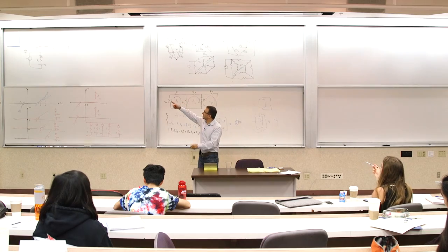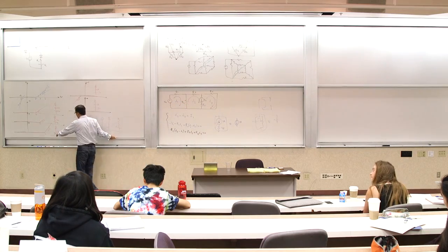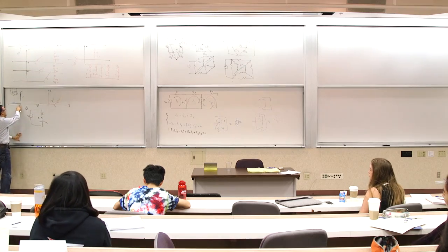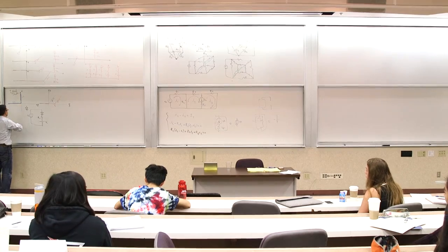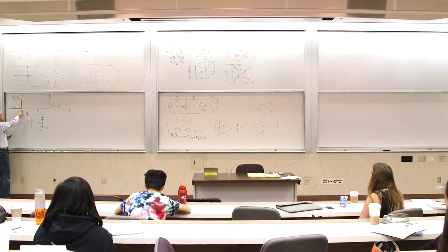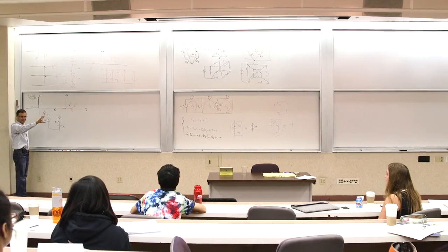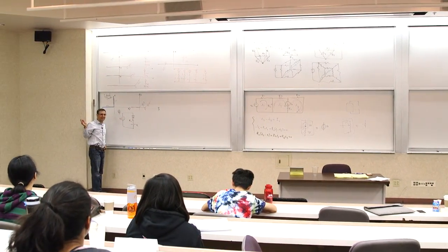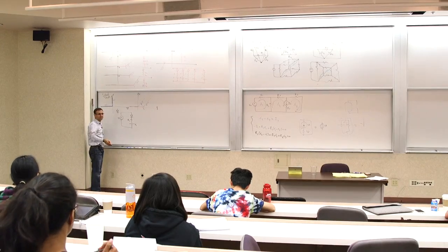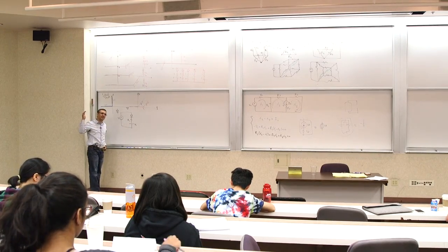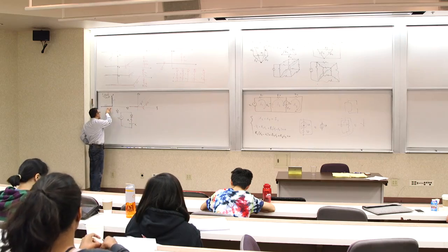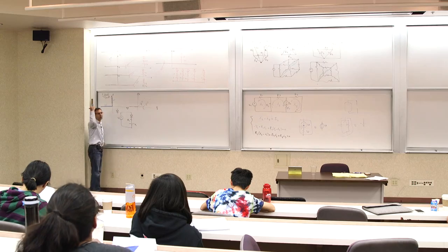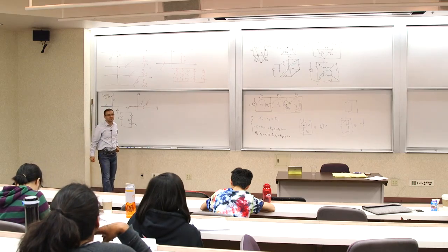Yeah. So the voltage across the diode can be anything, right? When you have an open circuit. That's a good question, right? So if you have no forward voltage, if your voltage is reversed, it can be anything. The current is 0, so it can absorb any voltage. The same thing in the forward path. In the forward path, it can absorb any current. All it says is that my voltage is 0. I'm a short circuit. I don't care. You can pass any current you want through me. And in the reverse, it says, my current is 0. Drop whatever voltage you want across me. So that's how it works.